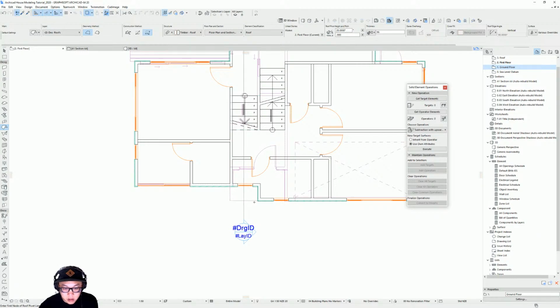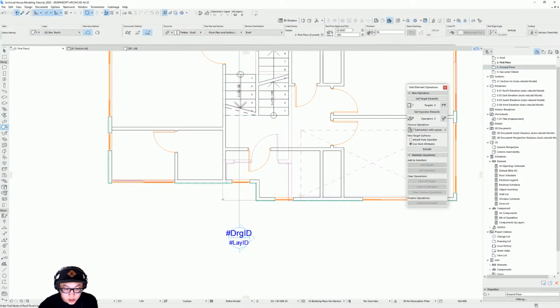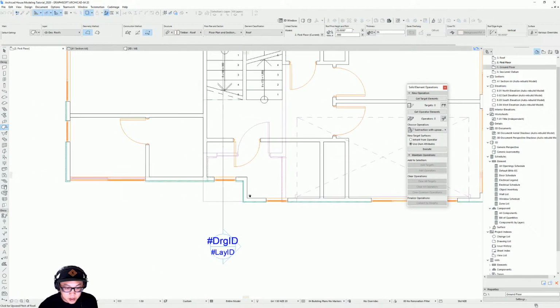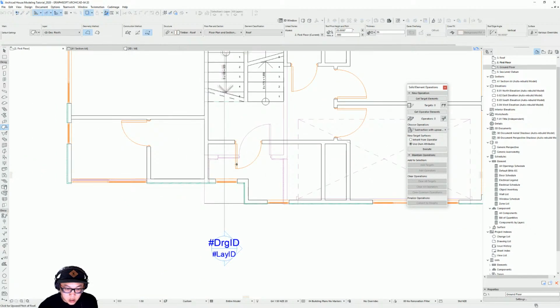so I know the width, roughly the width of the porch entry. And I'm gonna do this. I'm pressing shift to keep it straight. This is the bottom part. It's gonna go up. That's gonna be the bottom, and I'm just gonna do that for now. And I need to shift it a bit out. So there's like a little overhang, and let's do 300, and it's gonna go 300 that side, and maybe 300 that side as well.